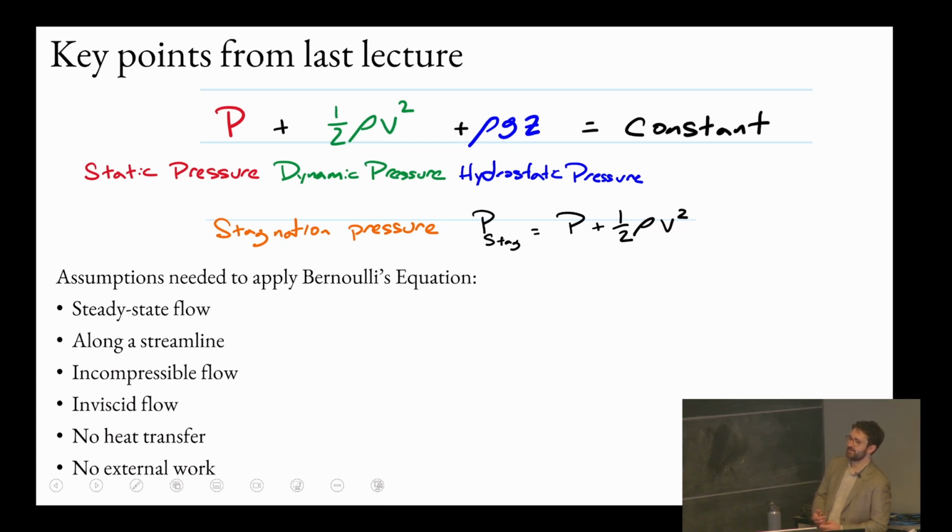I think the wind tunnel engineer yesterday was mentioning they use Bernoulli's equation in some parts of the wind tunnel. For example, they use pitot tubes to measure the wind speed. So there are certain parts of that flow that Bernoulli's equation applies to and parts that it doesn't. I will say there are many times where this is applied beyond this list. The point of a lot of things in this course is to give you the strictest assumptions. Then in practice, with better knowledge of the problem, you have freedom to break these sometimes. But you don't have that freedom in this course, just to be clear.